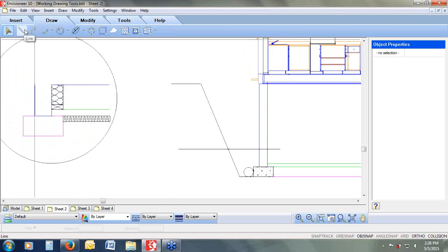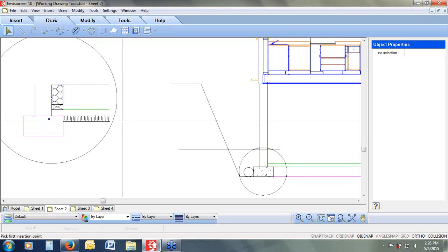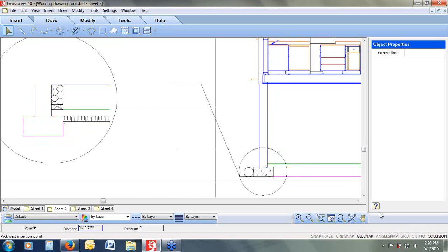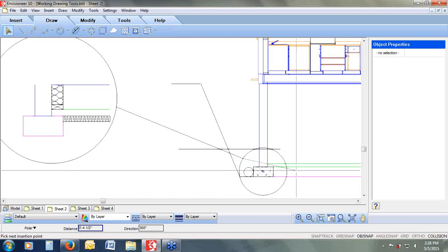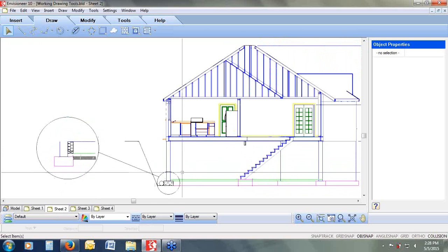And then I'm going to draw another circle around this area here and connect them with a line. From that circle, turning off my ortho, to that circle. Right-click, finish, indicating that this is a blown-up detail of that.